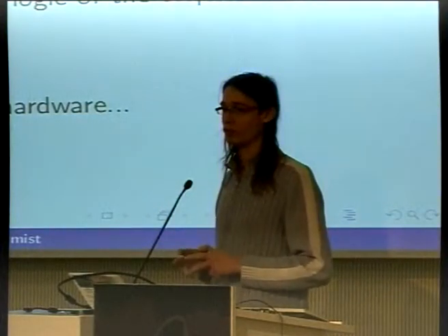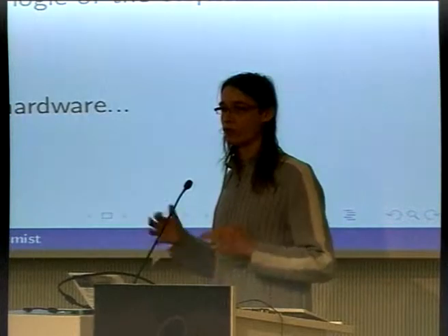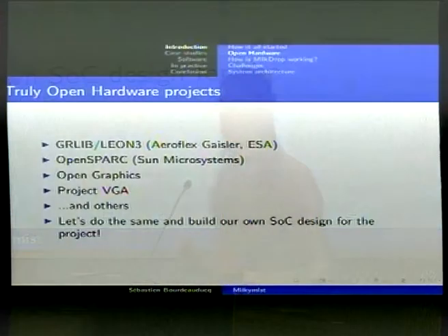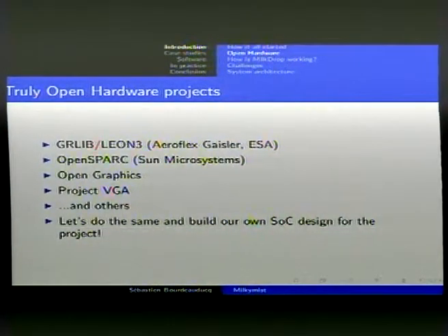For example, I spoke of video inputs, I spoke of MIDI, of DMX. If I wanted to interface all this using a Texas Instruments OMAP chip, this would get awful because I would need many other chips on the PCB to take care of all these interfaces. So there are already some other projects which have gone this way.